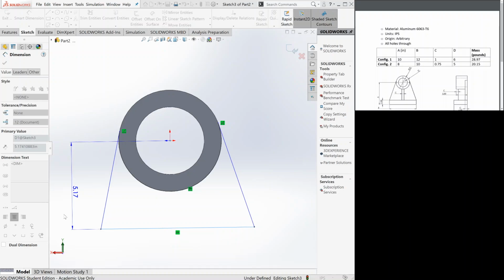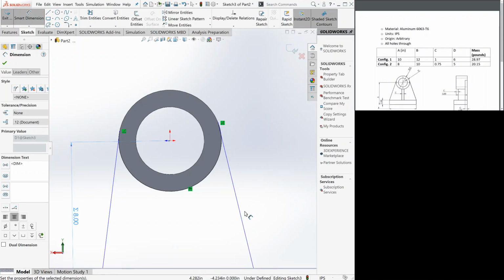So we're gonna write an equation that says a minus 2. Okay, so bear with me as we go. You're gonna click equals space a. You're gonna click on the a global variable. Okay, after that pops up, you space and then subtract 2. Click OK. And now we have our global variable set.